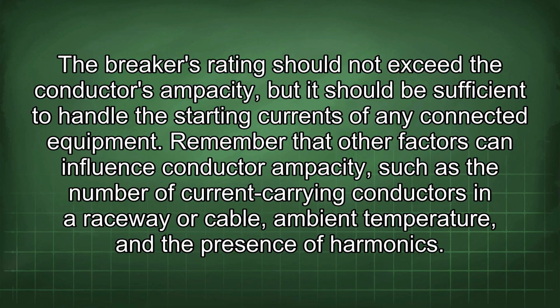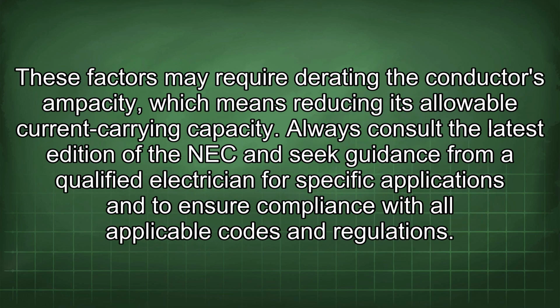Remember that other factors can influence conductor ampacity, such as the number of current-carrying conductors in a raceway or cable, ambient temperature, and the presence of harmonics. These factors may require derating the conductor's ampacity, which means reducing its allowable current carrying capacity. Always consult the latest edition of the NEC and seek guidance from a qualified electrician for specific applications and to ensure compliance with all applicable codes and regulations.